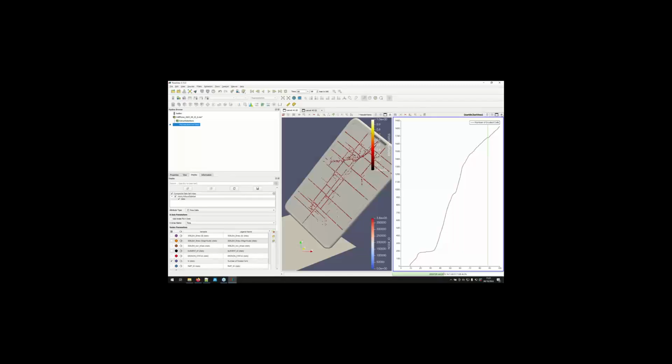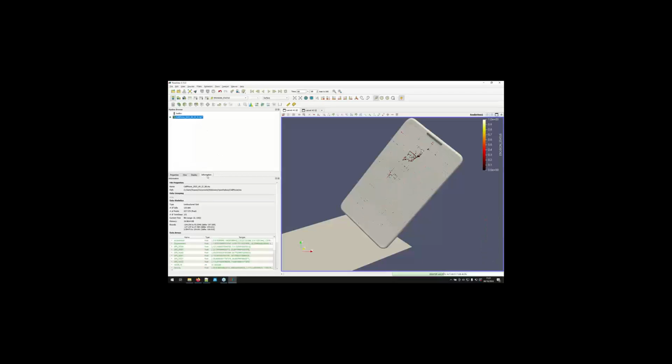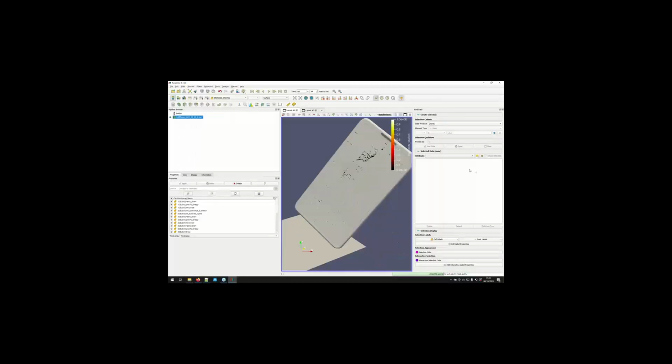Okay, so go back to the question about part extraction. So yes, this is definitely a relevant question, because by default in the VTK and VTU extraction, you have a huge unstructured grid with lots of cells. With the VTK HDF file format we are working on at Kitware, you will have automatic part extraction. But at the moment, we have to extract the part manually. So in order to do this part extraction, we will again use the find data in order to run some query on cells, because we have the part ID field, which is very convenient because each cell has a number which corresponds to the part it belongs to. So we can filter on it.